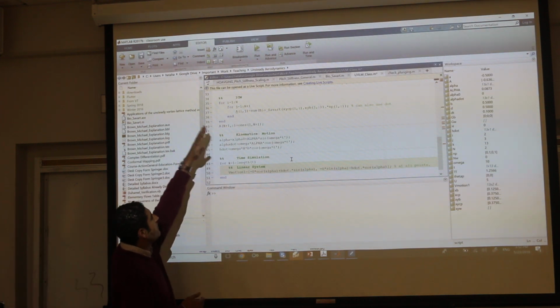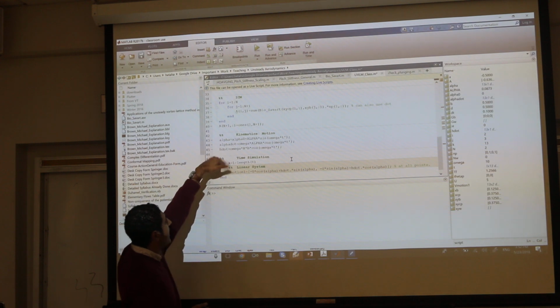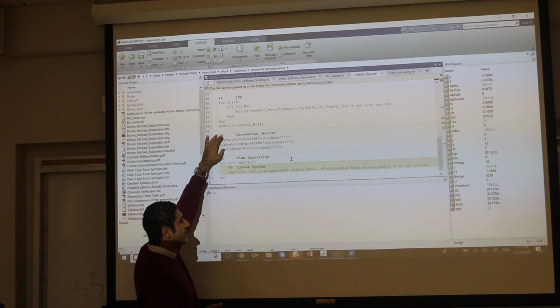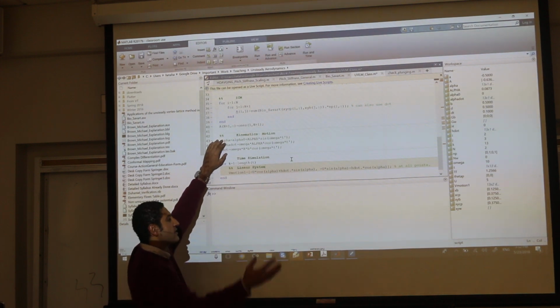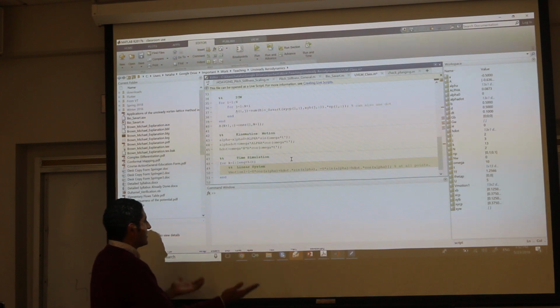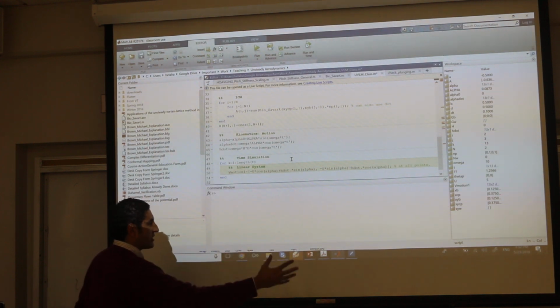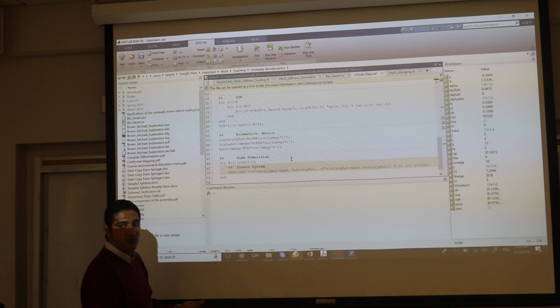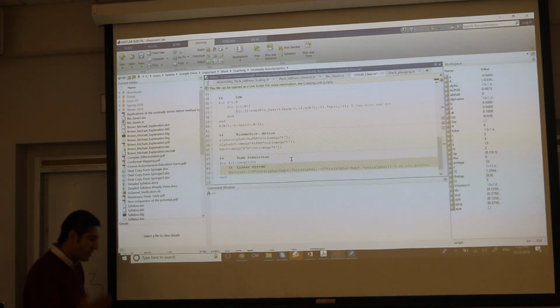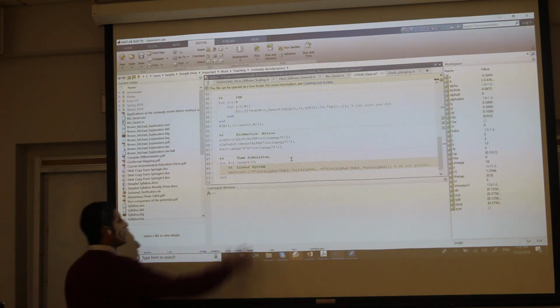Whatever we have here is just to construct the A matrix. And this kinematics, the motion, is to construct the right hand side. Everything is just trying to prepare this linear system, A gamma equals the right hand side, to get the gammas over the airfoil. Because if I have the gammas, then I solve my problem and I can do whatever. I can get the loads, I can get the velocity at any point if I want.